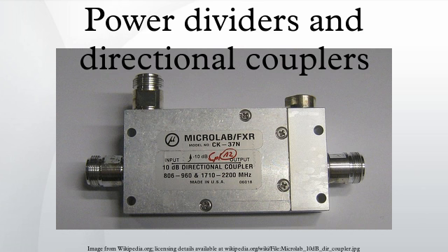Waveguide types: waveguide directional couplers, waveguide branch line coupler. The branch line coupler described above can also be implemented in waveguide. Bethe hole directional coupler. One of the most common, and simplest, waveguide directional couplers is the Bethe hole directional coupler. This consists of two parallel waveguides, one stacked on top of the other, with a hole between them. Some of the power from one guide is launched through the hole into the other. The Bethe hole coupler is another example of a backward coupler.